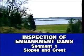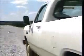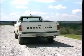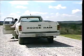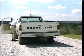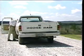Hello. You've just read about ways to inspect the slopes and crest of an embankment dam. Let's review. To inspect these portions of the dam properly, you must walk over the slope or crest as many times as required to see the entire surface area clearly. The sequence you follow to inspect the dam really isn't important. What's important is that you look at every part of the surface area on the entire dam.